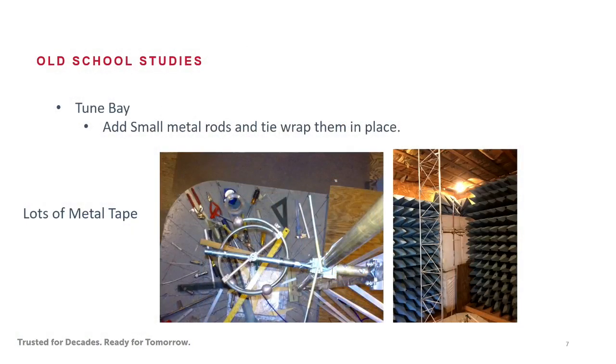So we finally built a model of the tower, and we get all the data that we can, and we model that, whether full size or at scale. And then we add an antenna bay, right, a radiating element to that. And we're trying to achieve a pattern, right? So the good news is we've got some experience at this, right? So we don't have to start from 0. We kind of have an idea of where that thing should go on the tower and what orientation it should be and how far off it's going to be and maybe how many different parasitic elements will be needed to make that pattern, but you don't know until you build it and start taking some test data.